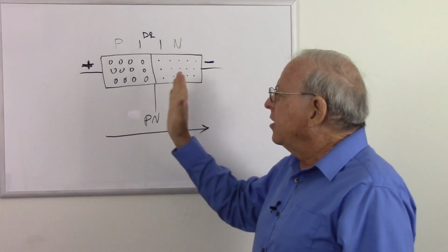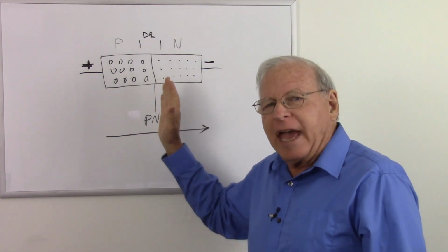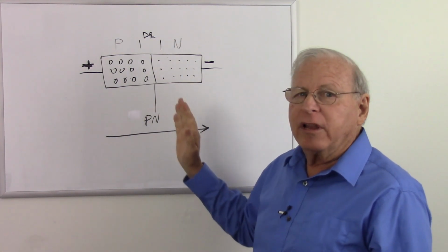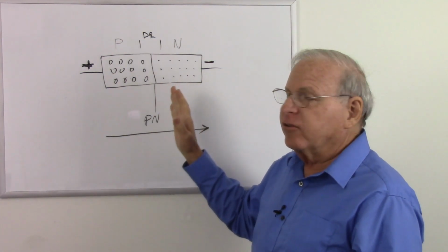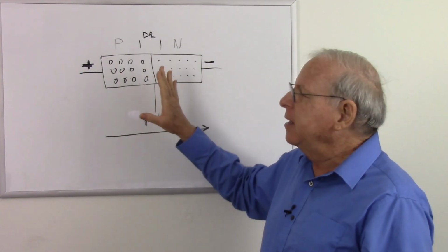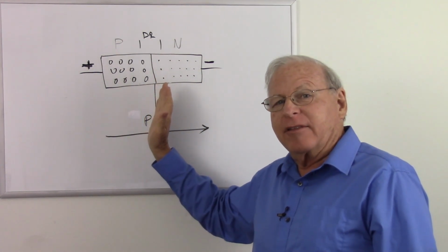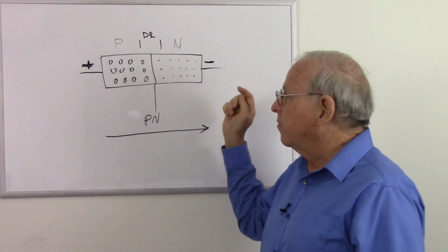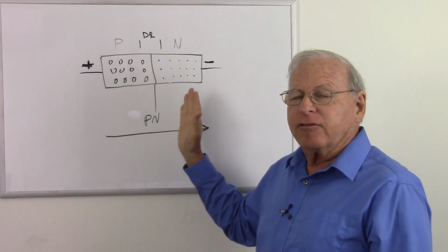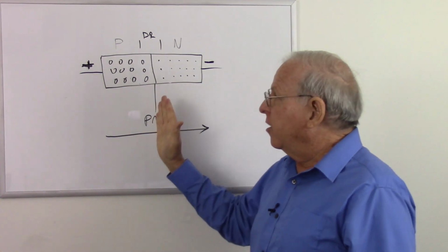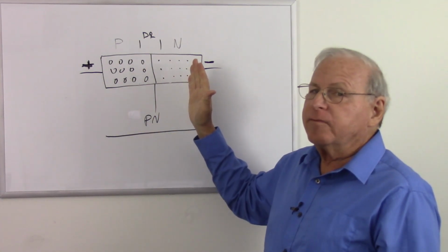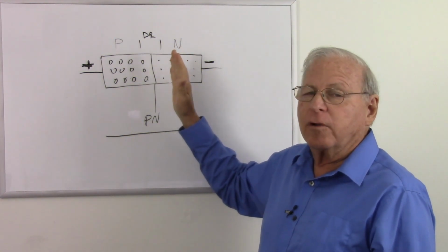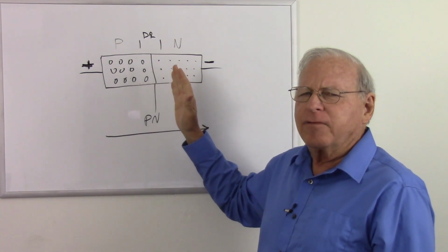So when we forward bias it and put enough voltage on there, it's going to start to conduct. This conducting begins to cascade and become a major conducting at about 0.7 volts for silicon and about 0.3 volts for germanium. But as I talked about, that's not etched in stone. Typically, you will find those voltages on a forward biased diode, but as you get more and more current, that voltage will get higher, and some diodes can have much more than 0.7 of a volt, even more than a volt and a half, 3 volts.